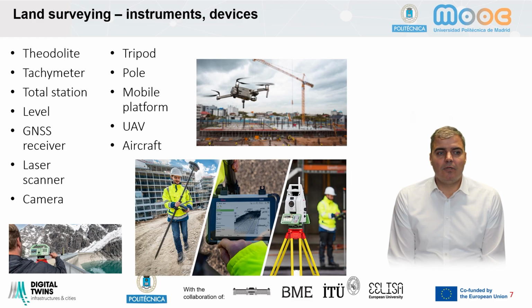And where to put the equipment, what kind of devices are we using? We can use tripods, we can put laser scanners, cameras, total stations on them. We can use poles for GNSS measurements. We can mount the sensors on mobile platforms. We can use UAVs or drones, unmanned aerial vehicles, and we are using them in the AEC industry, or we can obviously use more sophisticated aircraft like helicopters or conventional airplanes for airborne mapping.